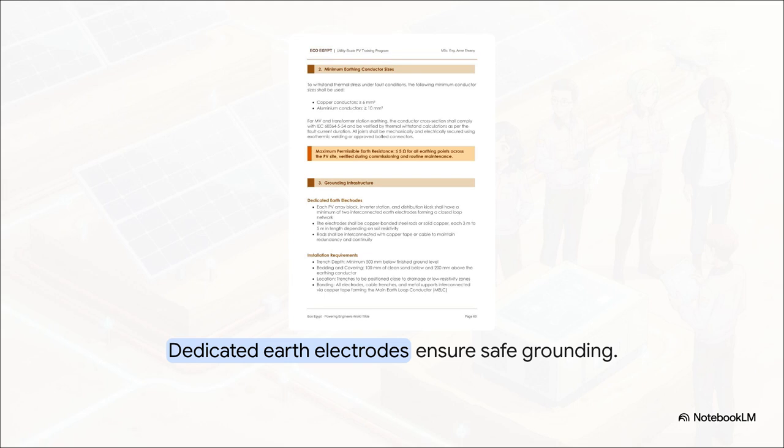Well, when it comes to the physical hardware, your dedicated earth electrodes aren't just any random metal poles you found lying around. They have to be specialized copper-bonded steel rods, or solid copper, typically around 3 to 5 meters long. And notice the redundancy requirement here. You need at least 2 interconnected electrodes for every single PV array block. Why? Because if one connection fails, or maybe it corrodes over the 25-year lifespan of the plant, that second one ensures the system stays safely grounded.